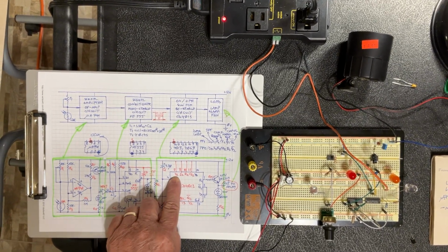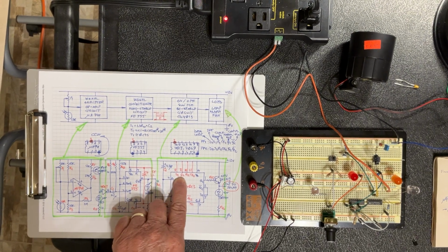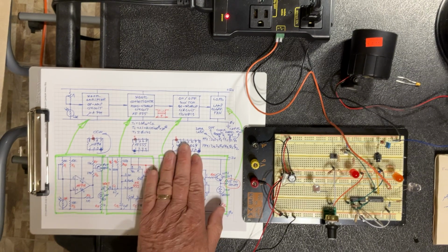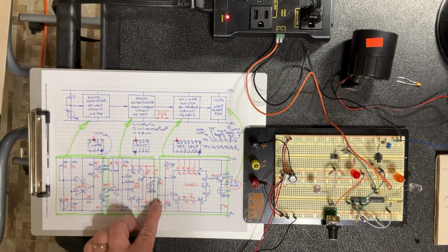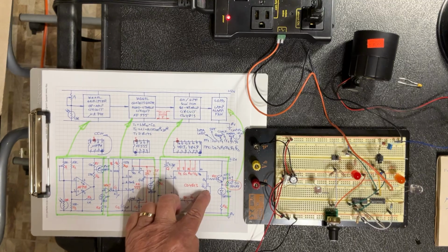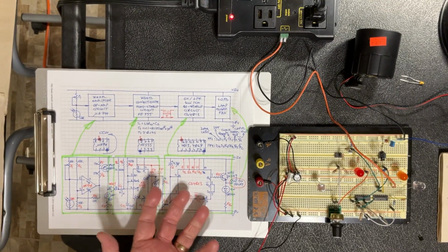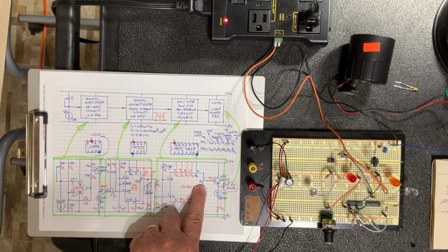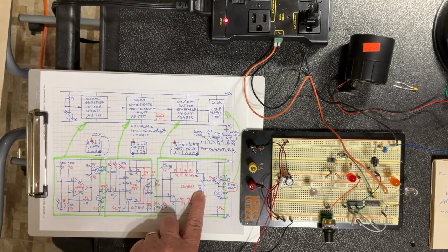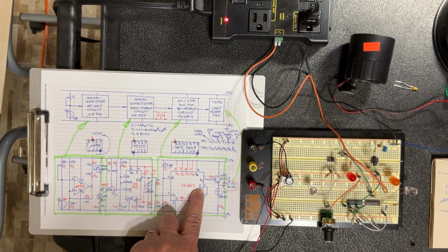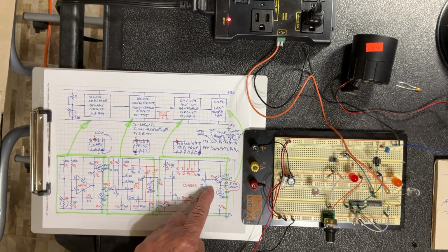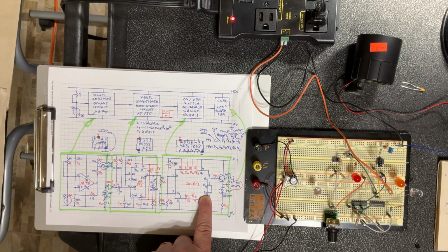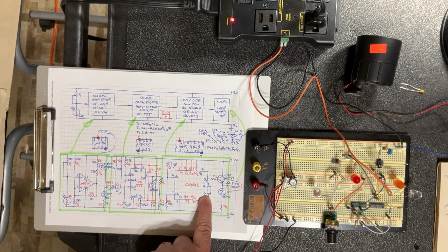This is why D2, S and R2, and clock number 2, all of them are linked to the +5, because we only need the pins which are in blue. And how the signal goes on and off is that it doesn't matter what the normal output Q1 is. The Q1 with the bar on top is the opposite of it. So it's going to take that signal and bring it to the data input. So next time, if it was on, it's going to be triggered off, and so on.